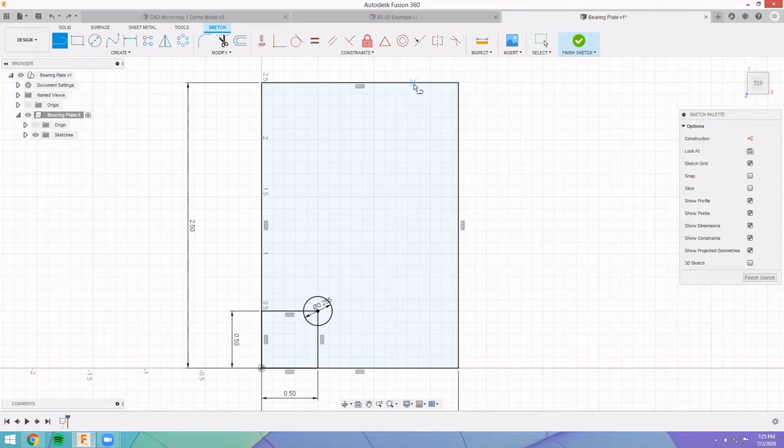You'll notice that the cursor is changed to an X. X also means coincident, but it means that the first point of this line that I'm about to draw, I just want to be intersecting this top line, but I don't really care where it is. Which again is similar, closer to what we're trying to do, but not exactly. What we want to do is make a line that's exactly halfway down this piece so that the left and the right can be symmetrical.